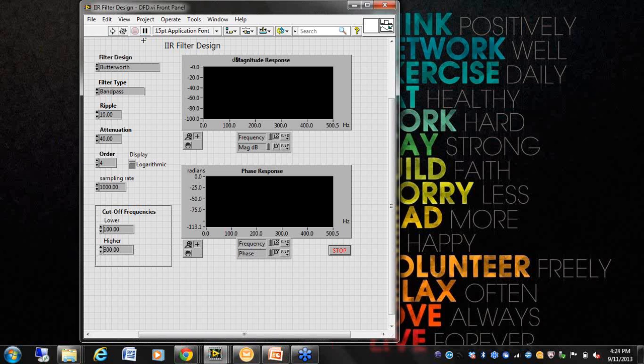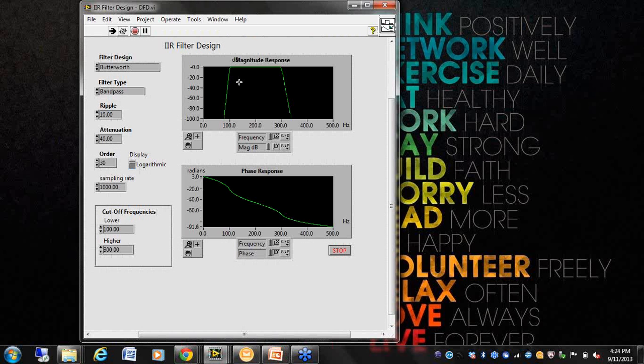The default I would like to set is Butterworth. You can quickly have a look, I've defined the order. Let me put an order higher than this because it's too small an order. I think I'll put 30. And okay, let's just run the code. Right, so what I have in front of me is a Butterworth response.